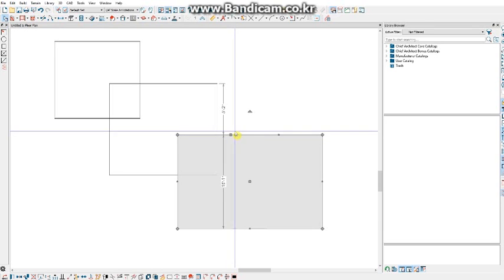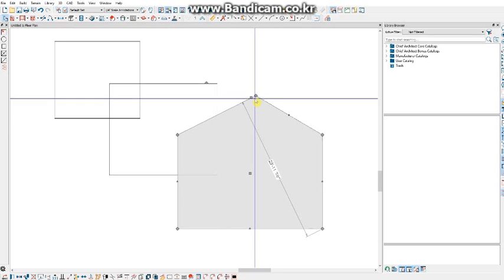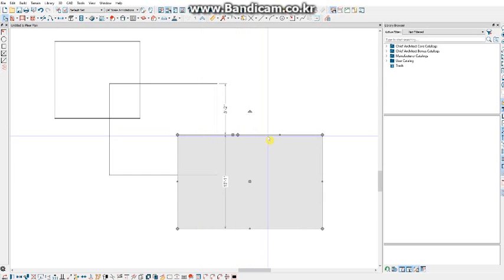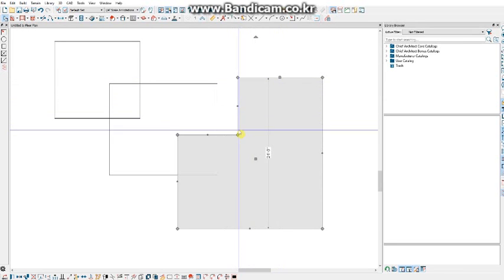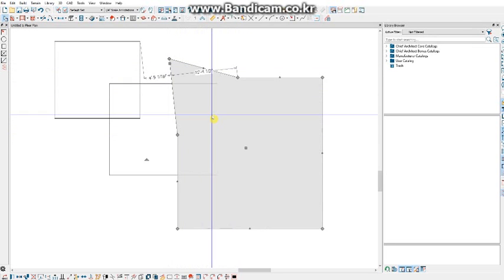Wherever I click, it'll create a diamond edit handle. This is now a break point. If I click and drag that diamond away from the polygon, it'll reshape the polygon and that will become a corner. If I drag that back so that the point is in line with these 2 lines, and then select one of these line segment edges and drag it away, it'll create 2 corners where that breakpoint was. Again, you can use the diamond-shaped edit handles to reshape your polyline.